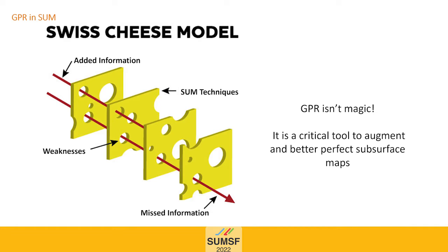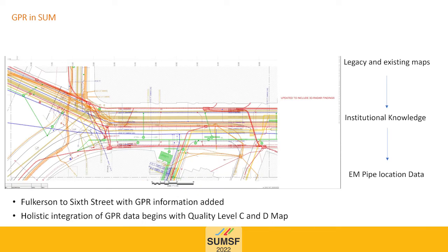If anybody is out there telling you that GPR will find every pipe, metal, non-metal, everything in the earth, they are lying to you. You can't see everything. It is not replacing any of the previous techniques, it's augmenting them. And the 3D system is not replacing the 2D pushcart either. It's just augmenting it. It's better for certain situations and worse in other situations.